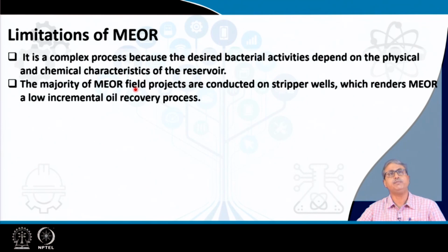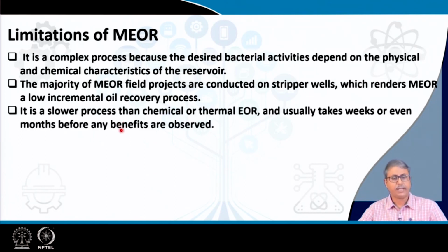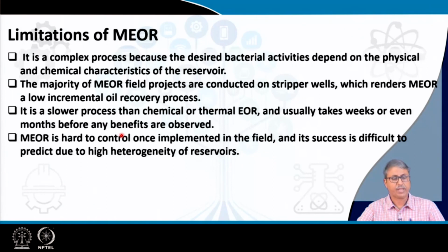The majority of the MEOR field projects are conducted on stripper wells, which renders MEOR a low incremental oil recovery process. It is a slower process than chemical or thermal EOR, and usually takes weeks or even months before any benefits are observed. So, those kinds of lag periods have to be allowed, and MEOR is hard to control once implemented in the field, and its success is difficult to predict due to the high heterogeneity of reservoirs.